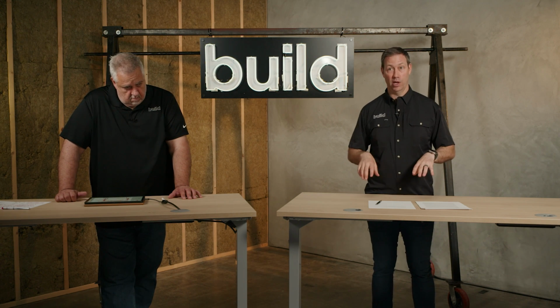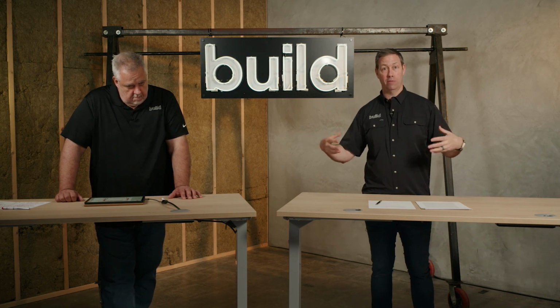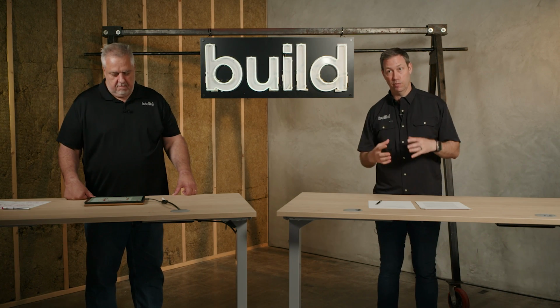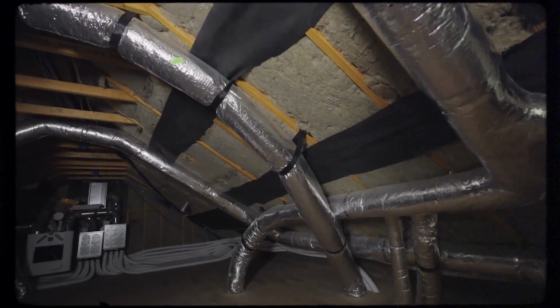The inside space means that air is going to have to come back and make up from somewhere else. And where does it make up? It makes up through all those little cuts and holes in our envelope. Sometimes that's around exterior outlets. Sometimes that's under the bottom plate of the house. But if that house is in a state of vacuum, of negative pressure because air is leaking out of that ductwork, it puts our house into a bad situation. So that continuity is really a big deal. And that's why I talk a lot about bringing our HVAC equipment into the inside space of the house.